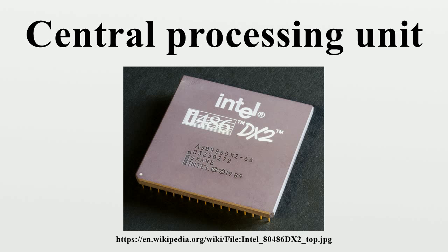Often, one group of bits within the instruction, called the opcode, indicates which operation is to be performed, while the remaining fields usually provide supplemental information required for the operation, such as the operands. Those operands may be specified as a constant value, or as the location of a value that may be a processor register or a memory address, as determined by some addressing mode.